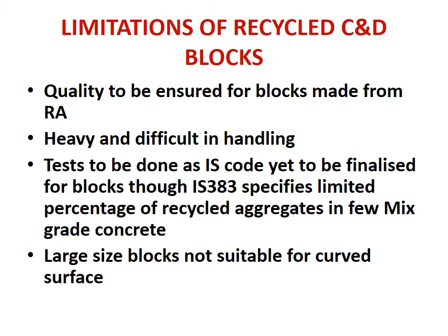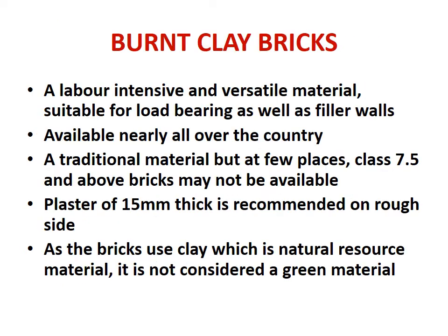Then tests are to be done as IS codes are yet to be finalized for recycled blocks, though IS 383 specifies a limited percentage of recycled aggregates in a few mixed grade concretes. And large size blocks are there. If they are manufactured in large size, then they may not be suitable for curved surfaces. So these are some of the limitations.